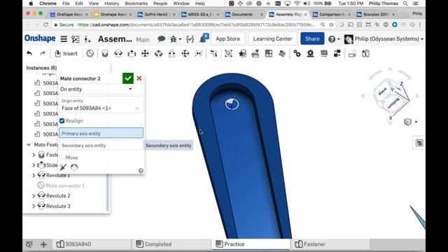I didn't join Solidworks until '97, so that decision had already been made. But in every machine tool and 3D printer in the world, up is positive Z. So in Onshape, the primary axis is Z. RGB, primary axis is Z, that's the blue one. That is the axis by default around which two parts will rotate. They rotate about Z by default.